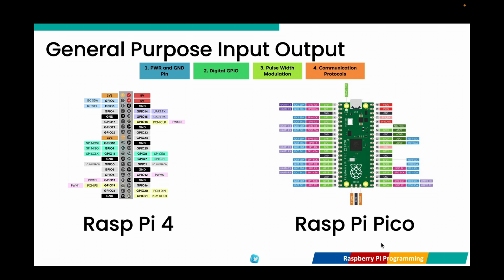Raspberry Pi 4 has one primary UART with an additional software configurable UART, while Raspberry Pi Pico has two UARTs with more flexible pin assignment. Raspberry Pi 4 has a more structured GPIOs layout with dedicated 5-volt pins, hardware PWM, and I2C or SPI or UART channels. Whereas Raspberry Pi Pico has more flexible pin assignments, supports analog input ADC, and introduces programmable I/O (PIO) for custom communication protocols.